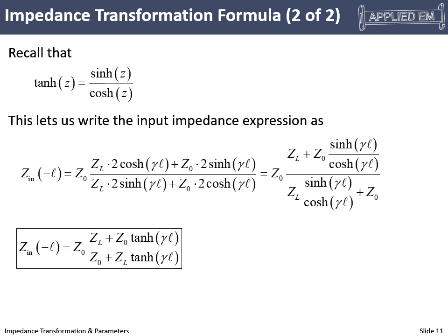And that is our final equation for impedance transformation, backing away from the load. And we're putting a negative L in here just to remind us that this is actually physically a negative Z, but when we plug in L here, we're putting a positive number in there.